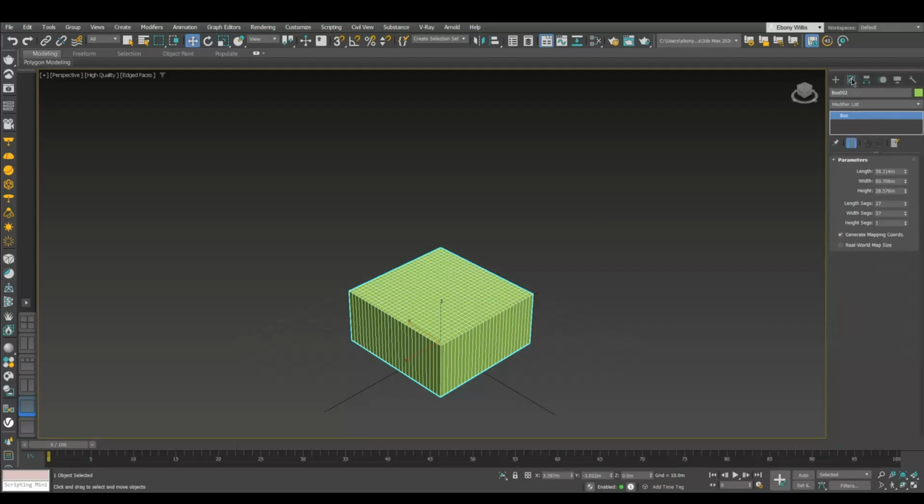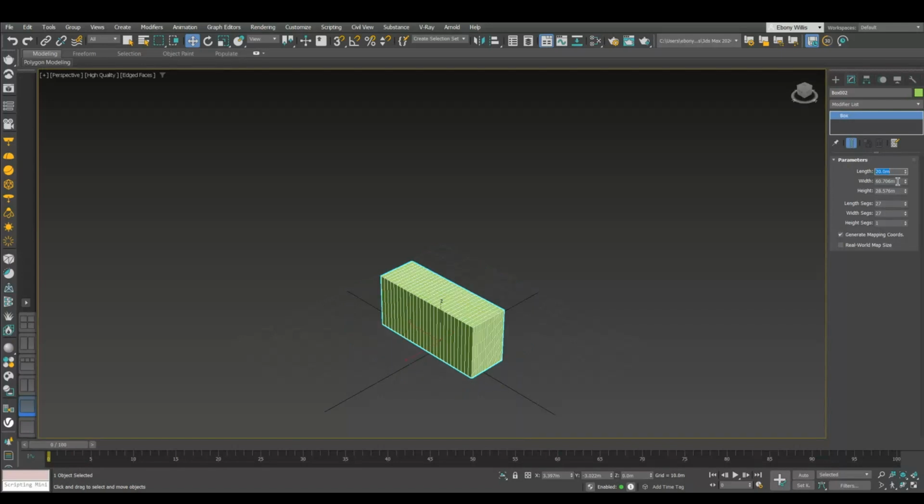If we just draw a simple box, then in the modify panel set the length, width and height values to an even 20 units to make a perfect cube. You can access Convert to Poly through the modelling ribbon, when you click the right quad menu, or the modify panel by clicking in the stack. It's also helpful to turn on Edged Faces using the shortcut F4.